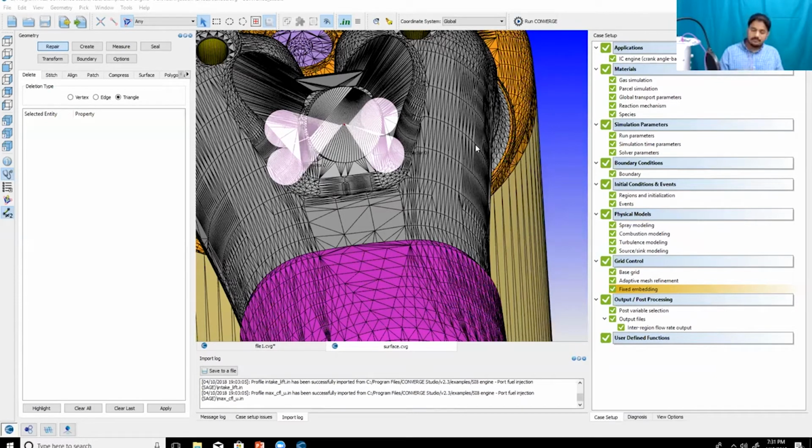And what you can do is, for adaptive mesh refinement, you can modify the SGS parameter, but you have to be a bit careful in that. But if you can do that, that would be a very consistent way of doing a grid dependence test.